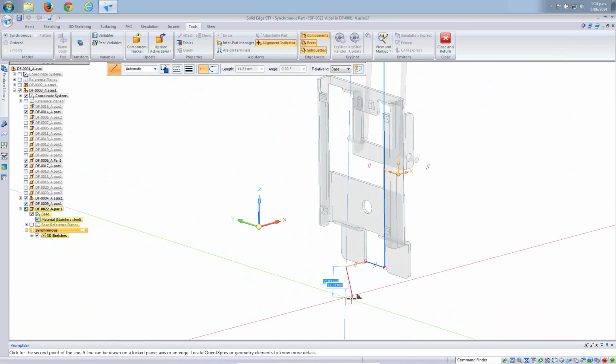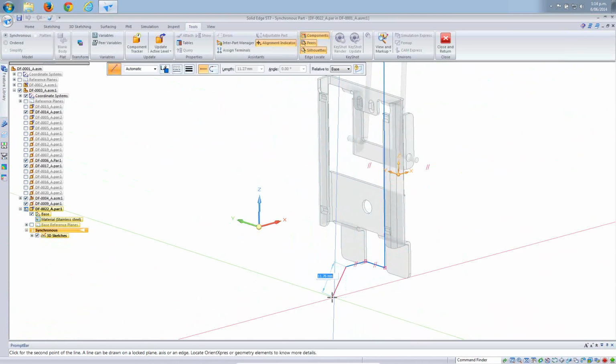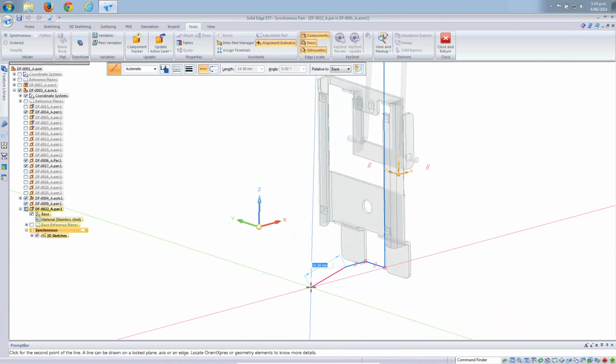And what we can see is Solid Edge is adding in connects between each of the lines, those little parallel lines as well. Next thing I want to do is create an arc. The sketch geometry I'm creating right now is half the model, and I'm going to mirror the second half of it. So this particular bit of geometry needs to be an arc, and I want it to be parallel with the XY plane from the triad.